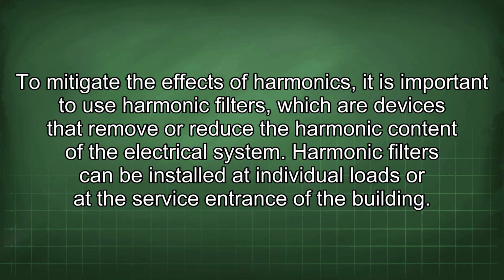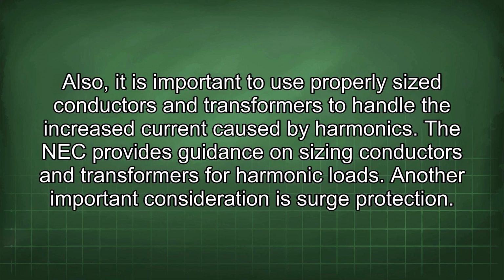Harmonic filters can be installed at individual loads or at the service entrance of the building. Also, it is important to use properly sized conductors and transformers to handle the increased current caused by harmonics. The NEC provides guidance on sizing conductors and transformers for harmonic loads.